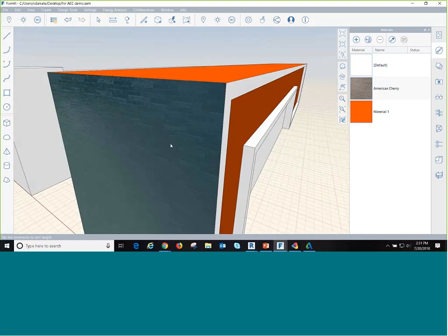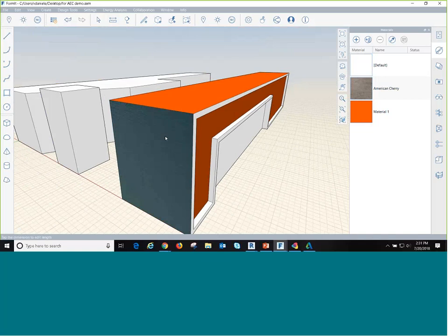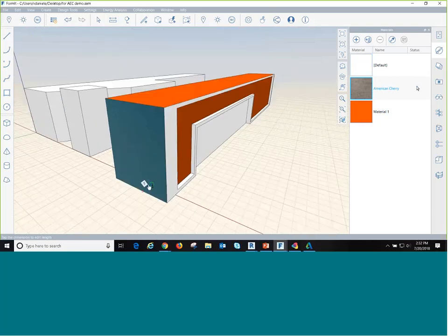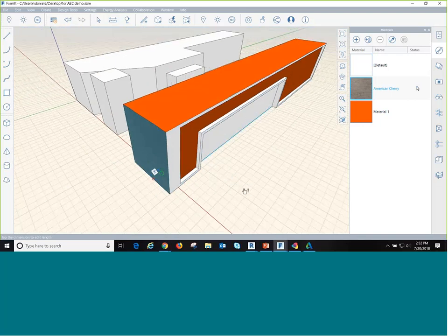But you can apply the same Autodesk materials to your Form objects, load them in, and Revit reads them with all the same values, like thermal properties, physical properties, so they are the same materials. So just as a best practice, if you're doing your conceptual modeling in Form, it's better to assign the materials in Form so that if you do change the model, you don't have to break those materials or reassign all of them.